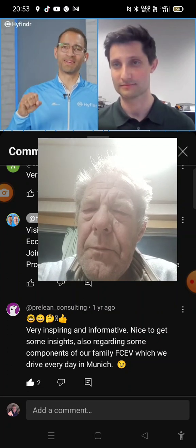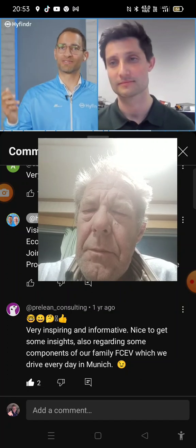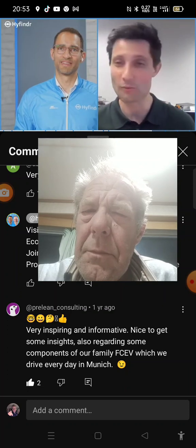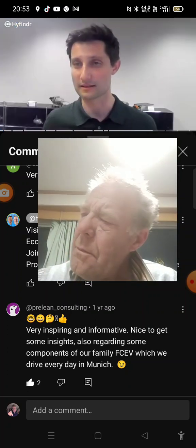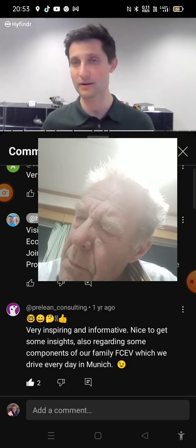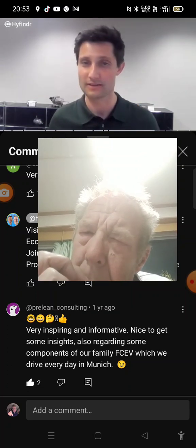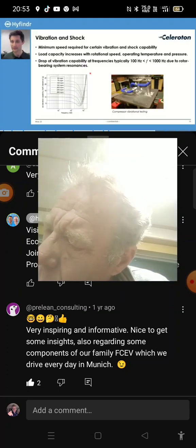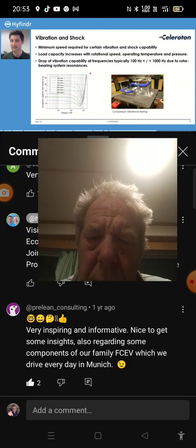What about load bearing? Sorry if I asked, but what if it's a very heavy shaft? Are these air bearings fine for that as well? Absolutely. You obviously need to design for it. The size increases, and there needs to be attention to how you design such a bearing. But in terms of forces, you can definitely design for larger shafts. For instance, here we tested up to 20 G acceleration, which means the forces of this rotor under acceleration are quite large.